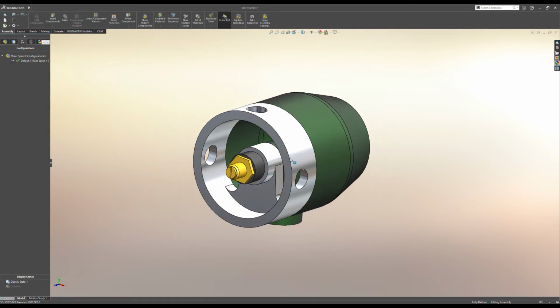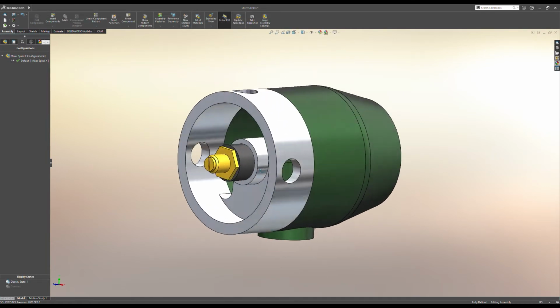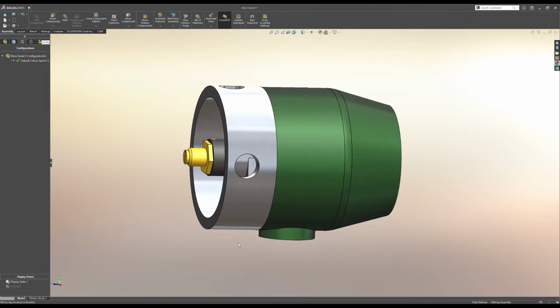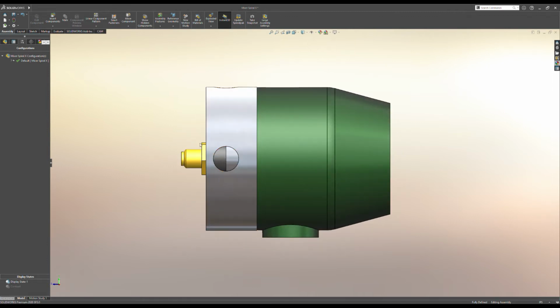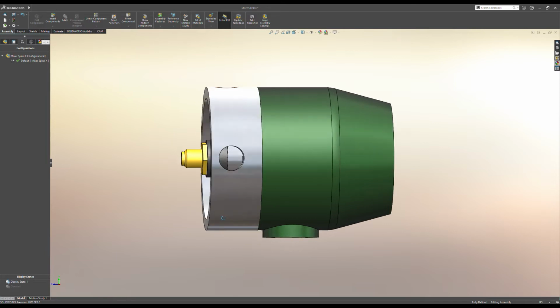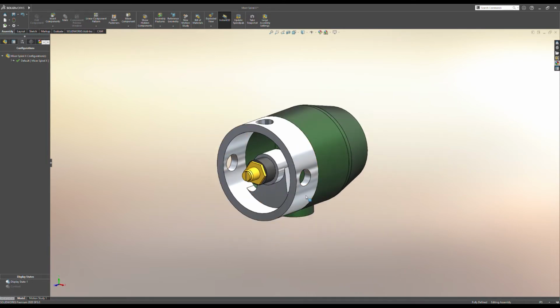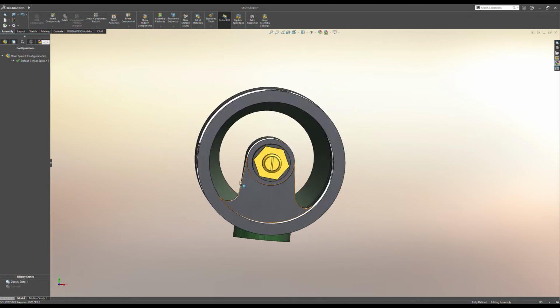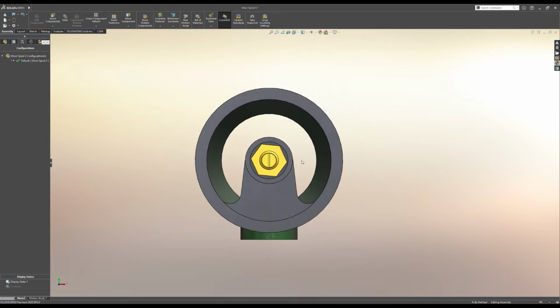So as you can see here, this is the fuel ring. It mounts on the back side of the mixer head, and it has ports for the BTEX to be injected. The air shutter will now be pushed back, and it mounts on the back side of the fuel ring. So the fuel ring is simply an adapter that mounts on the back side of the mixer head that allows us to inject BTEX into the natural draft of the mixer.